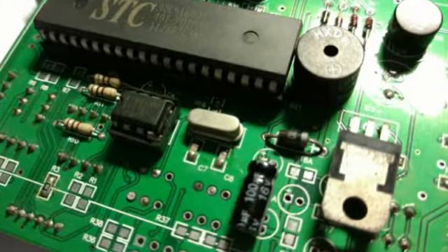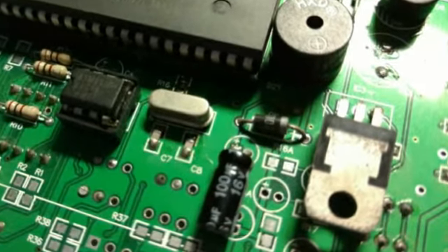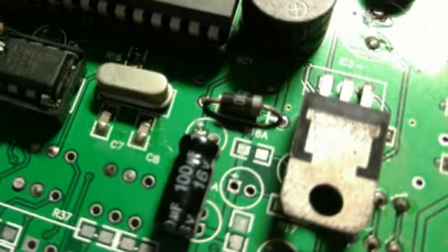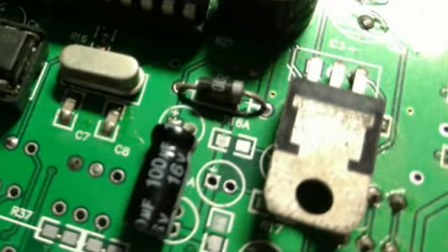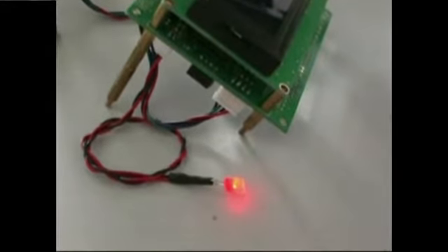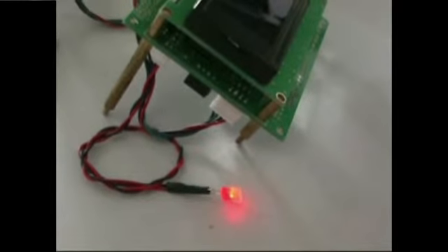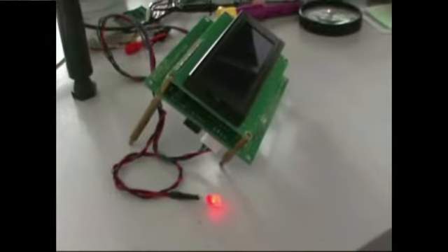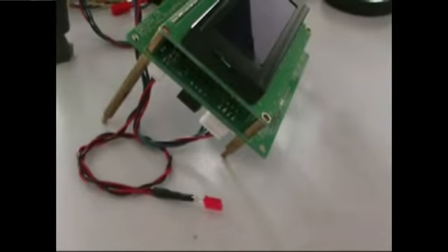I think we are using here a passive regulator, which is the LM7806, and then we drop down to plus 5 volts here, going into the microcontroller. And we also have an LED indicator. The purpose of this indicator is that when we power on the system, this LED, as controlled by the software, will blink or something, to indicate that the microcontroller is turned on and working functionally.